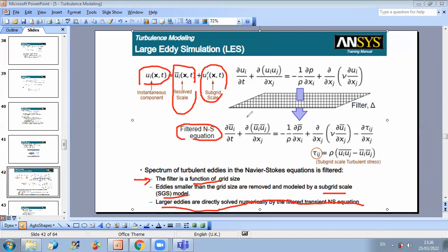And then we can have a differential equation to be solved for the filtered part. And for the remaining part, where we have more complex issues, we can use previous turbulence models developed. And of course, this method will present higher accuracy, because direct numerical simulation at the end is the most accurate way. If you can solve analytically the equations you have, you will get an exact solution.